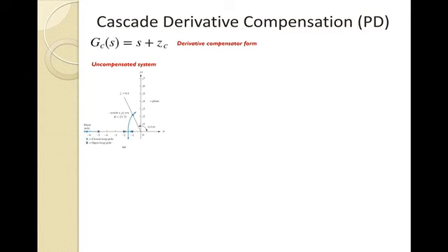And what I want to do, just for a visual as we work through some of this, is actually draw the system representation. So we're going to start by looking at our reference signal, R of S here. Now that is going to be coming in with a plus. There's going to be a feedback term here with a minus. Now we are going to look at our compensator, so our GC of S term right here, that's our compensator. And then we can call it our plant transfer function, our G of S, it's right there.